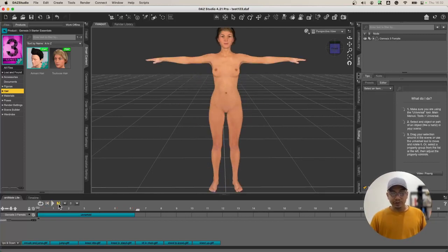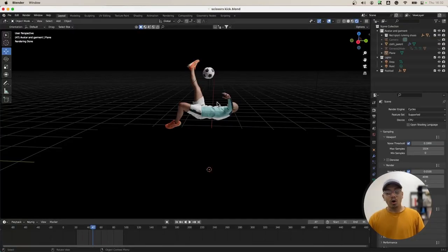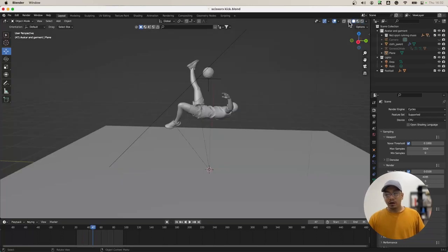Now, what you do is you take this animation to software like Blender or Flow or any other software, right? So now you just have the avatar, you have nothing else, okay? Now you're going to take that to Flow or Browzwear, because now you need to do cloth simulation, okay? Once you take that to Flow, you need to bring the garment file from Flow to Blender and bring this avatar file from DAZ to Blender, and you have to combine those two parts together.